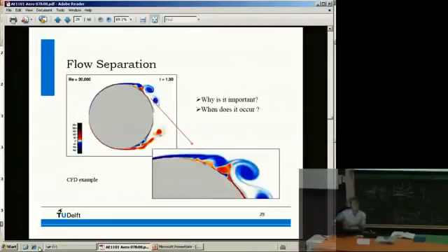Now the next concept, so this is laminar, turbulence and transition. Now we move to a different concept that flows can do: separate. And this is also a viscous effect. So if you have viscosity in your flow, small changes locally can make your flow separate. Why does it separate? Well, it is separating because it's fighting a positive pressure gradient. So the pressure is increasing and increasing and increasing. At some point it says, I'm not fighting the pressure anymore, I just go straight on. So the flow is not attached anymore but separated.